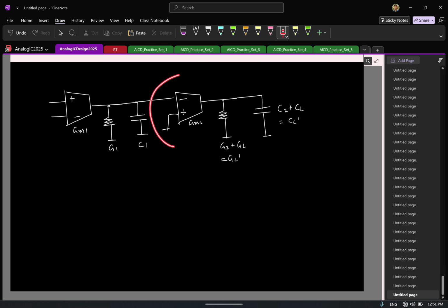Yeah, remember, how will you implement this? This is taking one input, amplifying, and giving a single output. What is the simplest way to realize this? Common source. What is the gain of a common source amplifier? Minus gm times R0. I include the negative sign to capture it, otherwise at a block level it doesn't make a difference. Okay.